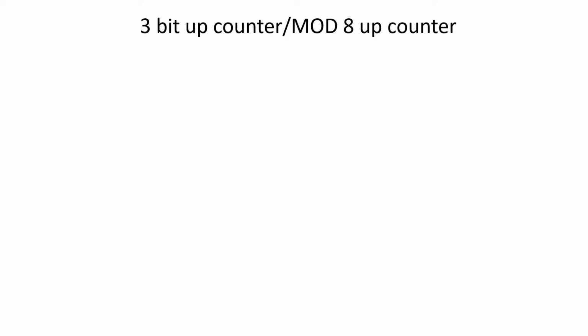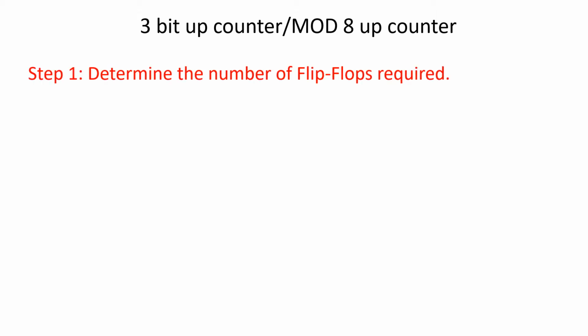We will design 3-bit up counter. It is also known as mod 8 up counter. We will follow step 1, which says determine the number of flip-flops required. Since we are going to design 3-bit up counter, we are going to need 3 flip-flops.